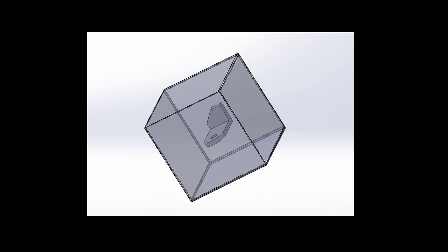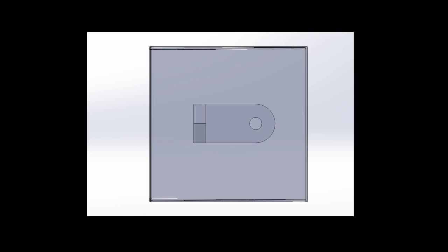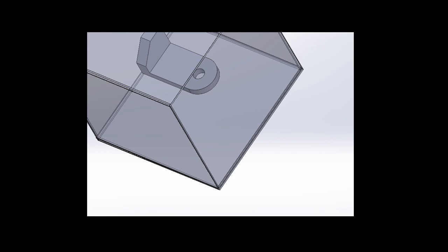And now we are limited to the 6 different views, which can be labeled as top, front, right, bottom, left, back, etc. Look at the views inside the box and how helpful they are in extracting information regarding the object. Will it be easier to convey information regarding the object to a third party using the box's views or the dodecahedron's views? That is not to say that all of the dodecahedron's views are useless. All these other views other than the 6 principal views are commonly referred to as the auxiliary views. We will discuss why they are used further in this lecture.